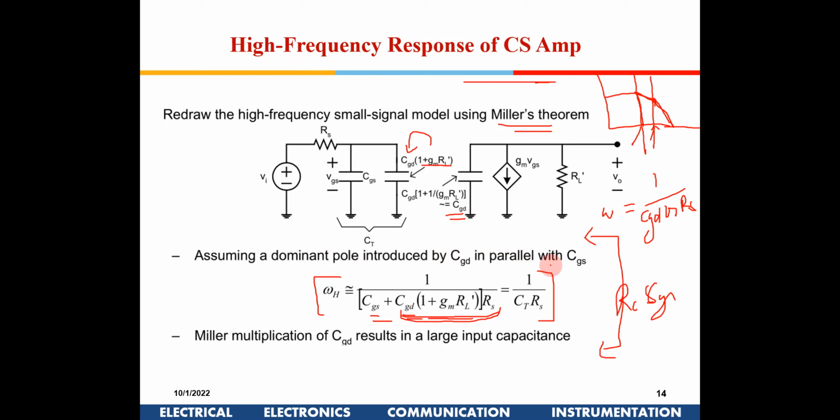Sir, you have mentioned you will clear the 20 and 40 thing. So now is it possible, or at the end you will clear? No. What do you want to know? Sir, as we discussed, after one pole, we will have 20 dB per decade. Yes. Then after the second pole, there will be 40 dB. So my question was, after each pole, will 20 be added, or will the previous RC effect be added in the output of the second pole?